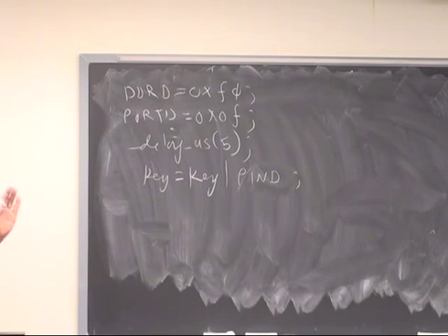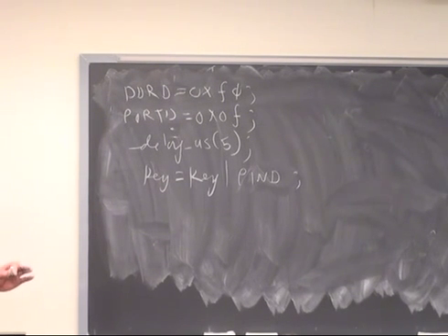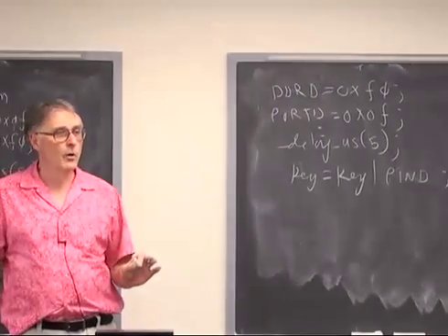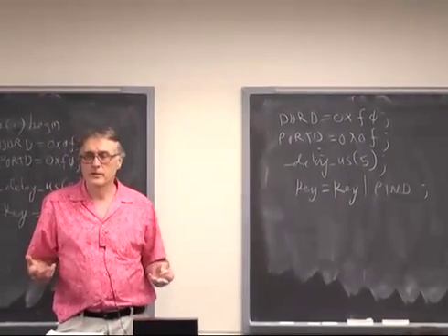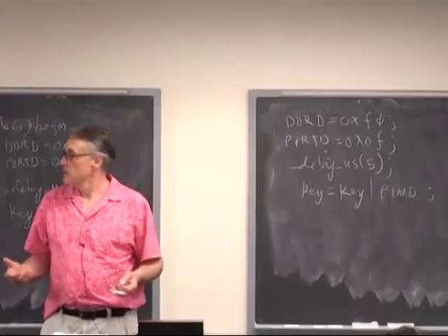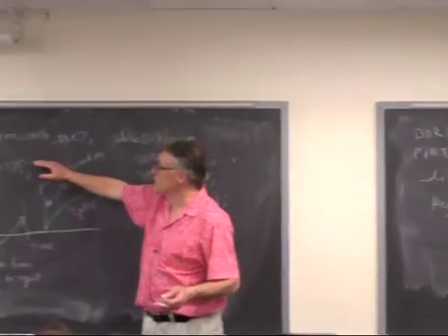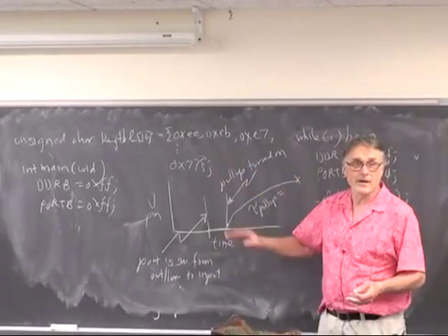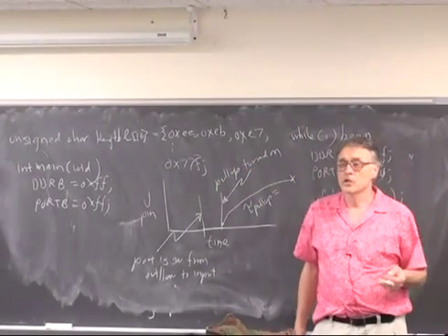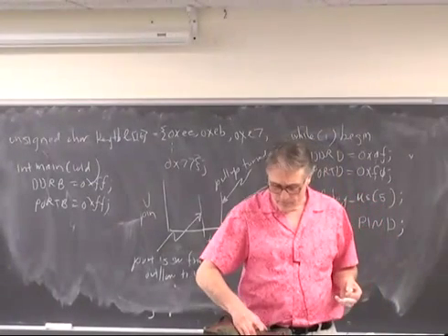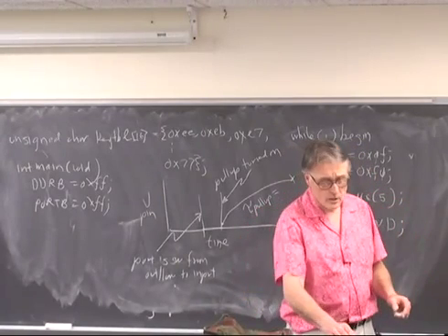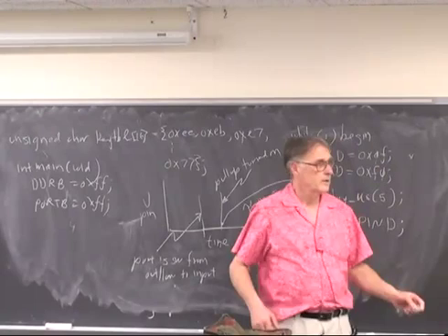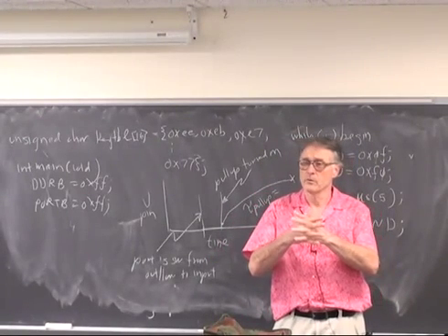Okay, at this point now we have a scan code. If no button is pushed, it's going to be FF. If more than one button is pushed, there's going to be more than one 0 in at least one of the nibbles. And otherwise, the value is going to fall into this 16-entry table up here. So we have to slide through the table and check for all of the values. I'm not going to do that right now because it's just slightly longer than I have left. So, we got 7 minutes. Any questions about Lab 2?